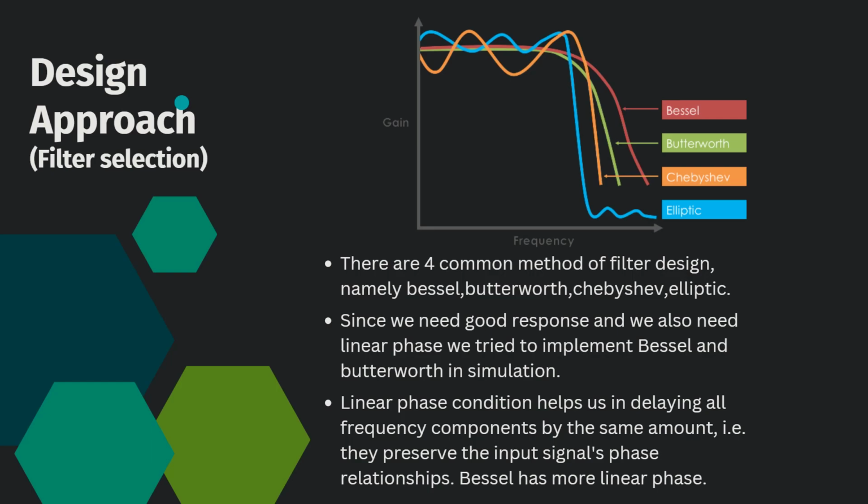As you see, we have attached calculations for all the filters which we used, for the low pass and for the high pass individually. So this is the Butterworth band pass filter. For the third order, it requires 4 op amps. As we are using a third order, we need to cascade a first order and a second order filter for the low pass. And coming to the individual calculations, those are attached already, as you see in the slides. This is the individual calculation for first order and second order, which belongs to a third order band pass filter.